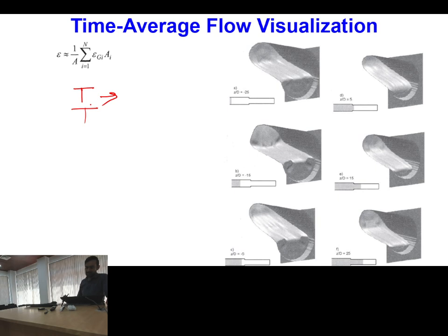So these are certain examples where, if this is your cross section of the tube, shown at a certain angle, then at this cross section your phase density function has a variation something like this at different locations. This is nothing but the corresponding values of the void fraction. Here you can see this type of structure means you have something like a stratified flow situation, where in the top portion you have one type of fluid, and in the bottom portion you have the other type of fluid, and you get the corresponding values of the void fractions.